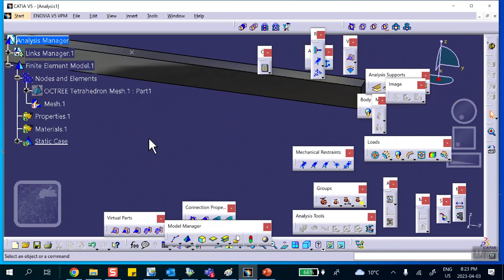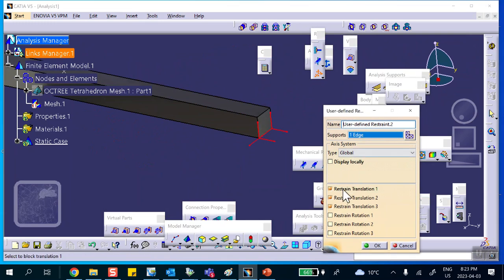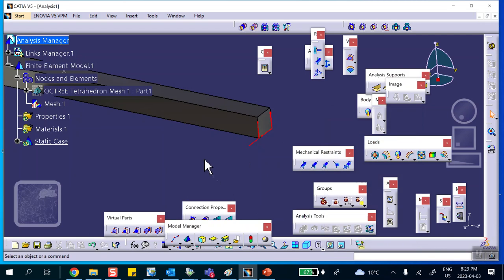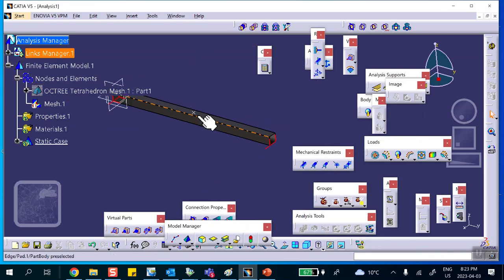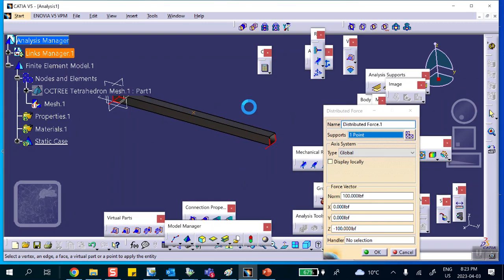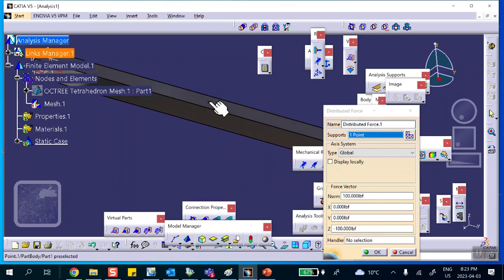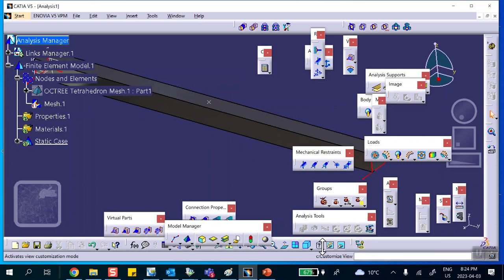And then on the other side, it's on a roller, so it can move in the Y direction, but it cannot move in X and Z. Okay, good. Now, we're going to apply load here, 100 pounds downward. So there's a force at that location. Now, because we already took into account that this becomes a node, the force is going to be placed at that node.